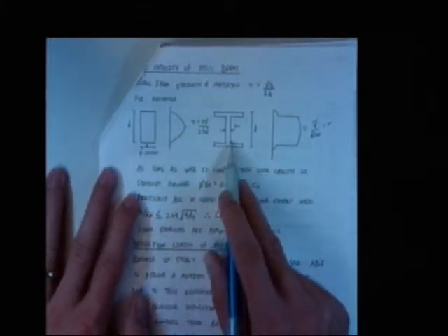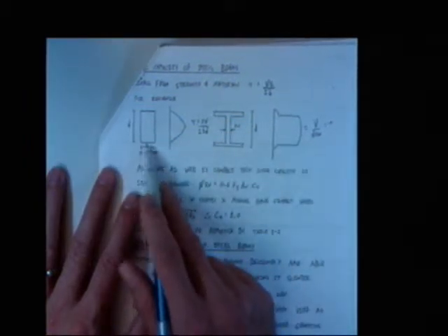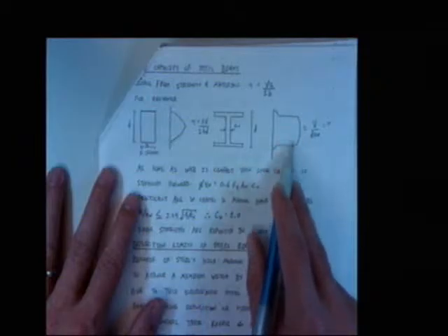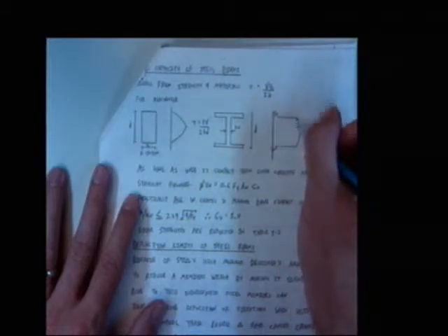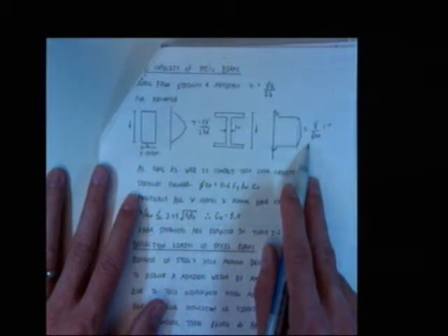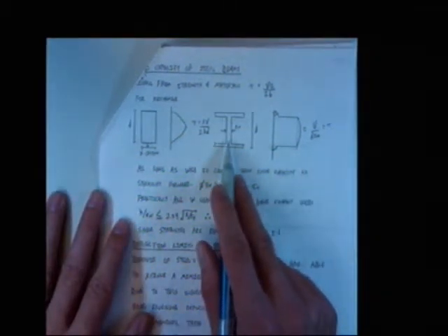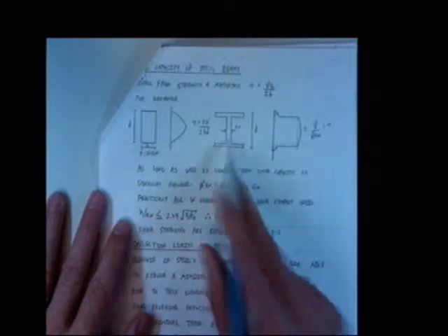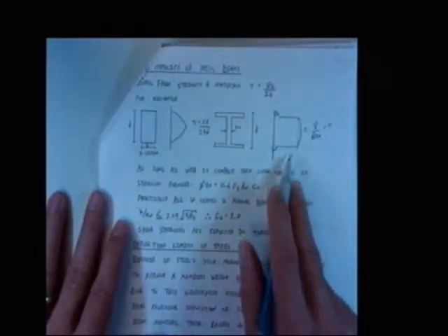For these sections that look something like this, that they're not nearly as wide, I get a much more uniform shear diagram, and I can ignore the nonlinearity here, and I approximate it as a constant value over something like V over A. Okay, and that works fine for things that are not wide, and that are tall. That's a decent assumption.